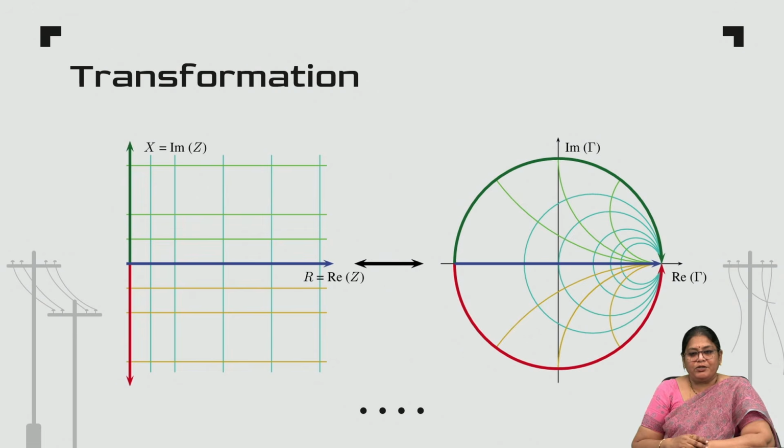Now, how do we transform that into a Smith chart? The Smith chart is the same thing. Whatever we represent in Cartesian, we use the same concept in a chart of circular fashion, which we can see over here. We use the upper half to represent the positive jX, and the bottom portion, the red colored one, indicates the minus jX term.